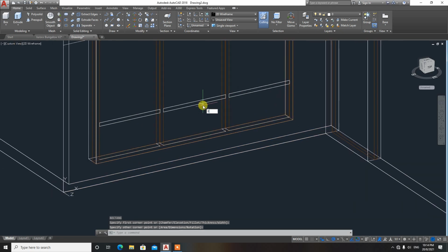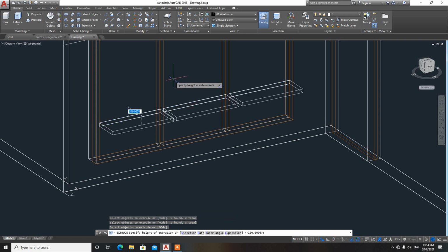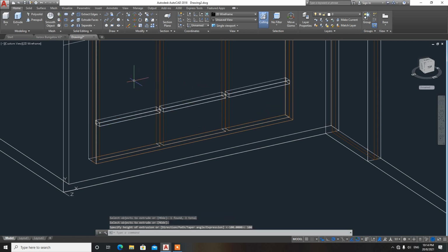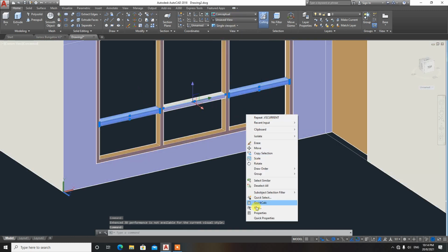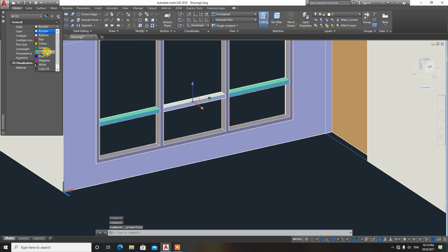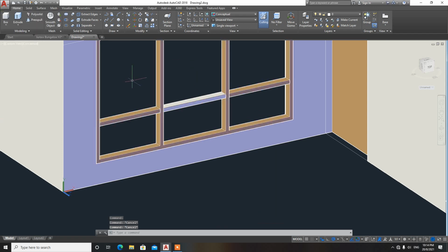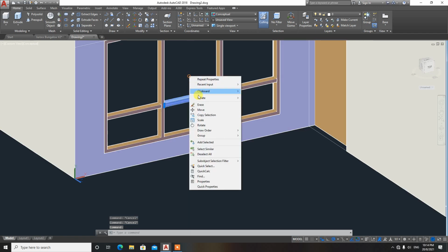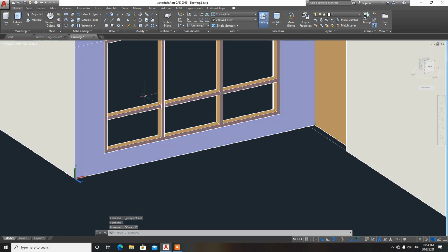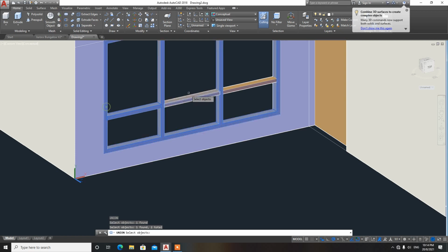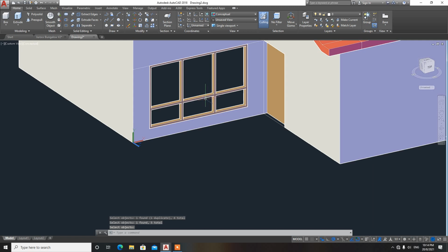and of course extrude this, enter, going inside 100, enter. Go to conceptual and change the color to combine it. Definitely a union command just to combine it. Type UNI, enter. You are able to combine this. So you got that already.